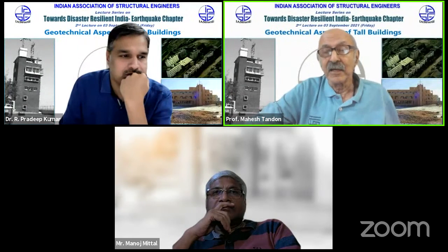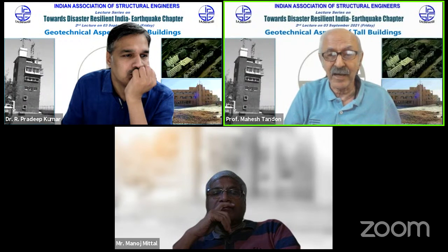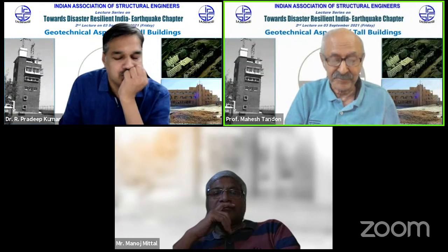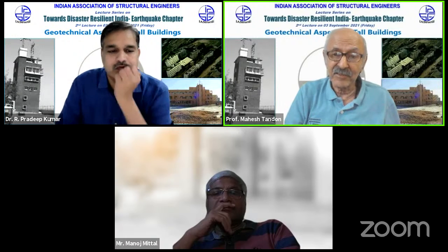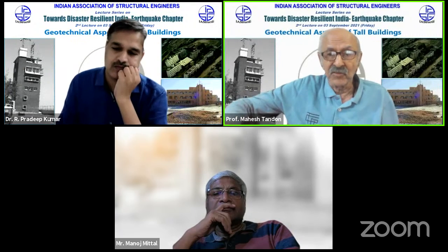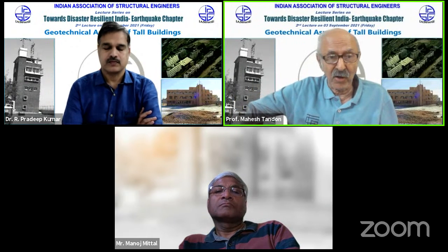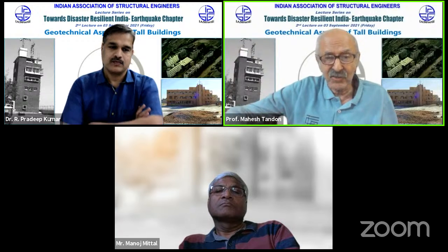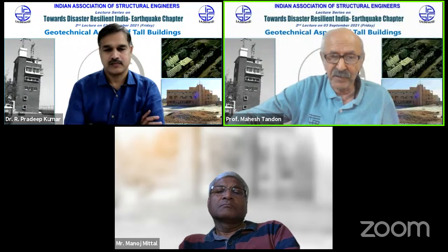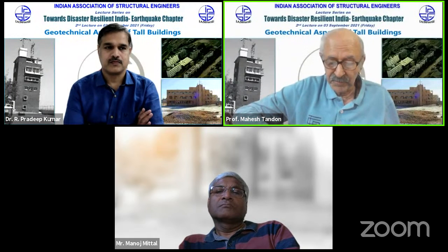And the other thing is that our map only gives you acceleration. It doesn't even tell you that those accelerations are at the rock level, which is somewhere way down. It depends on where the rock is. And there is an increase or enhancement of the shaking when you come to the surface. If you have a soil layer above the rock, then it is increased. And that part is not covered in our code, which is, I hope that the new code, which is under development, and we are having frequent meetings on it, will cover that also.